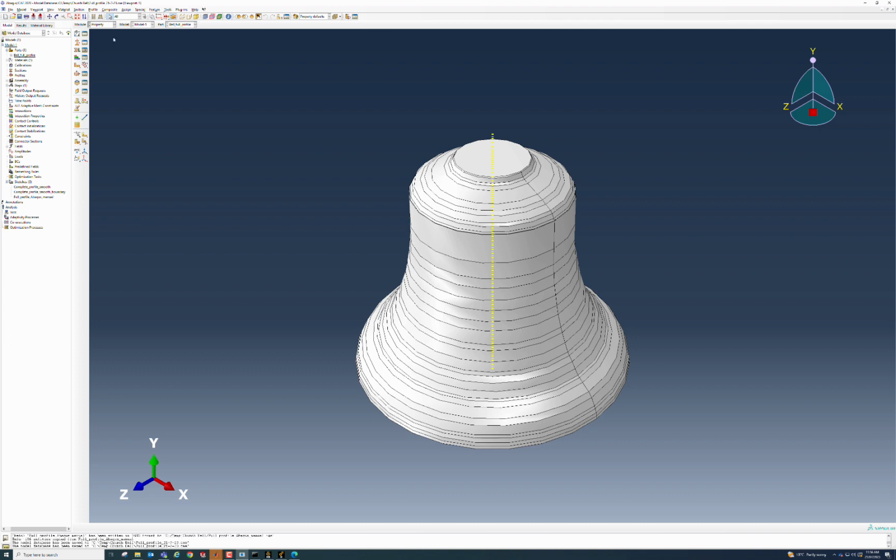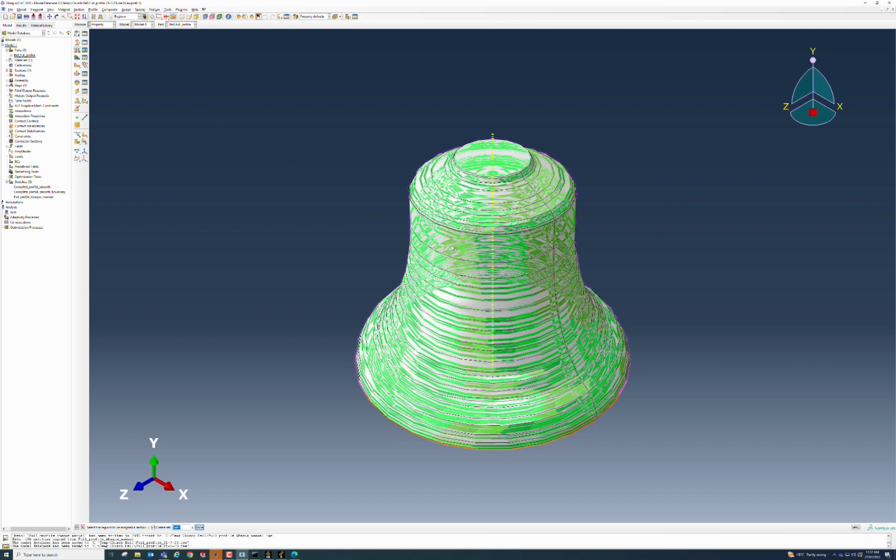So you'll notice that initially I've entered those values in a meters unit system. Subsequently, later in the video, when we have a look at the mass properties, I'm narrating this retrospectively, so I know what's happened in the future. I'll have to go back and change those material properties to be in kilograms per millimeter cubed, because we've defined in millimeters, and megapascals for the Young's modulus rather than gigapascals. So those are the unit systems when we're modeling in millimeters to be used in Abaqus.